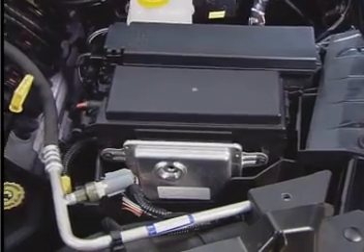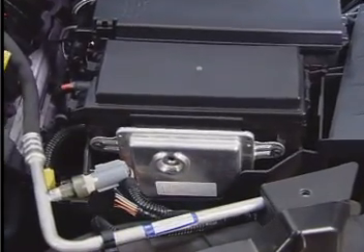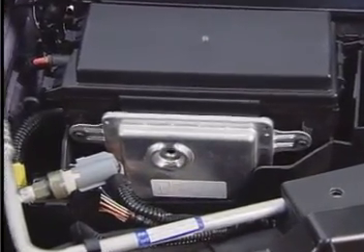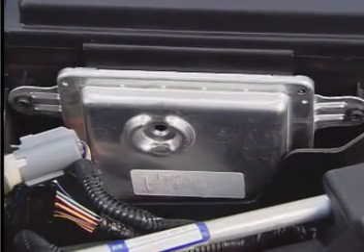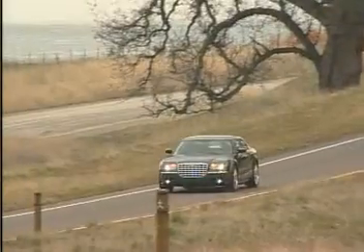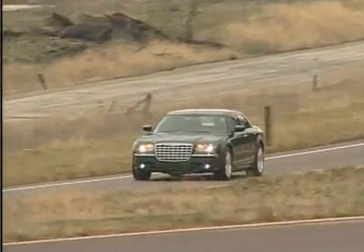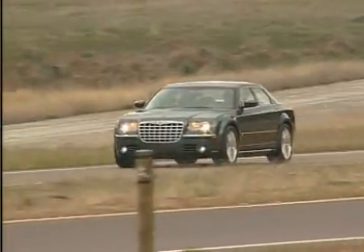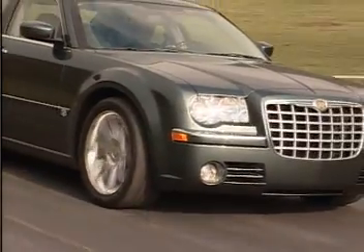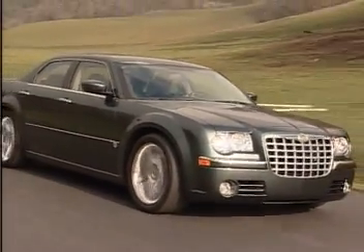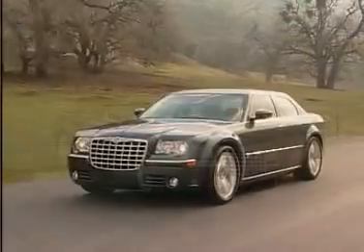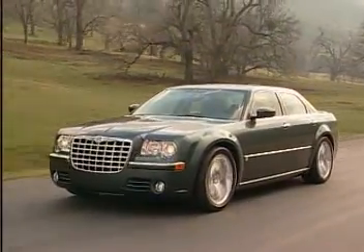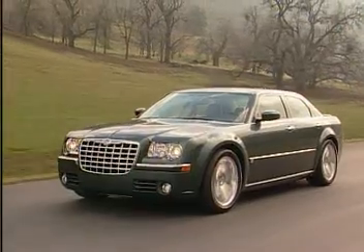On Durango, one thing the CAN-B, CAN-C, and CAN-C Diagnostic buses have in common is that the central gateway controller is part of all of them. Future CAN bus applications will not necessarily incorporate the central gateway in the box for the front control module, but they will use a gateway module of some sort. In addition, you may see modules which are not gateway modules connected to more than one bus.